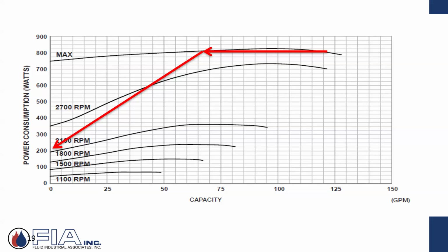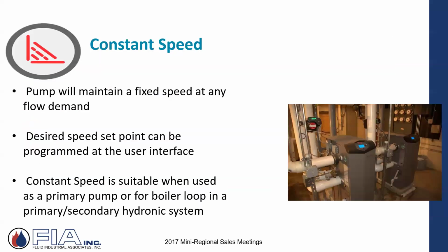But on these smaller applications, you're getting a lot of the benefit and a lot of that energy savings, and it's all right on board. And the beauty is that pump can then be used in the next building or the other application or down the street. Maybe it's delta T, maybe it's constant pressure. So you have all of that capability on these pumps.